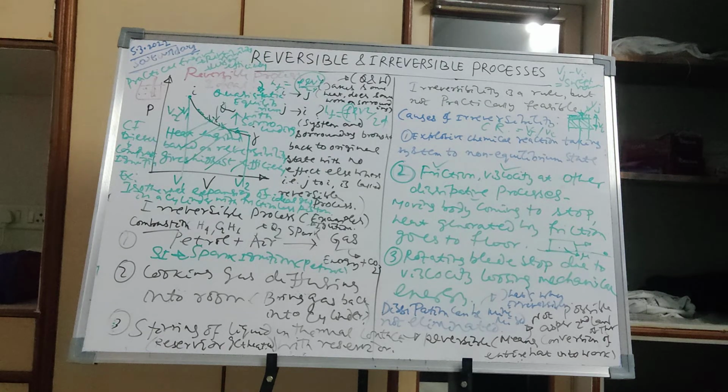Then why are we studying reversible processes, if no process is reversible? Because in the second law of thermodynamics we have seen that the efficiency can never be 100%. But what is the maximum efficiency? The maximum efficiency is possible only when the processes are reversible. An engine containing ideal processes will have maximum efficiency. It will not be one, but the efficiency will be the highest.